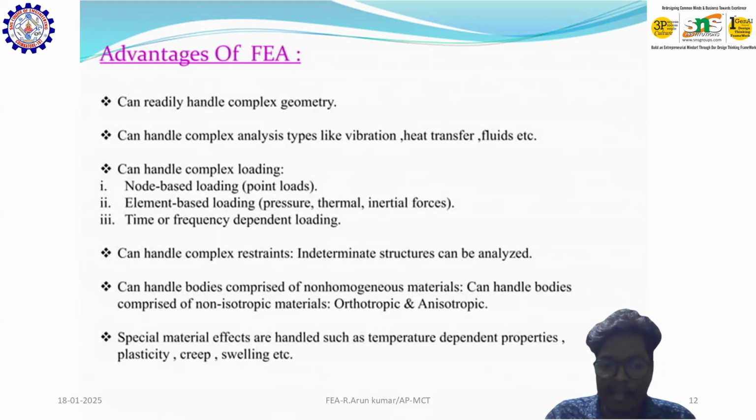It can handle complex restraints, and intermediate structures can also be analyzed. It can handle bodies composed of non-homogeneous materials, and bodies composed of non-isotropic materials like orthotropic or anisotropic. Special material effects are handled, like temperature-dependent properties, plasticity, creep, or swelling, etc.